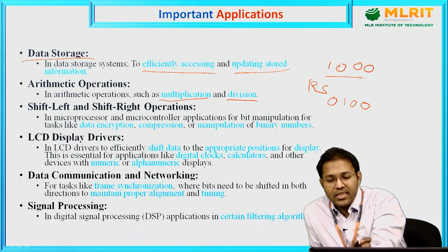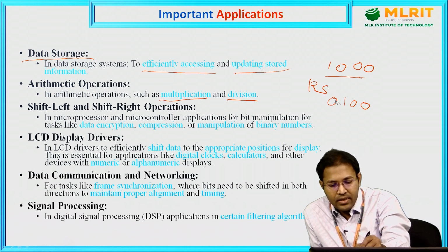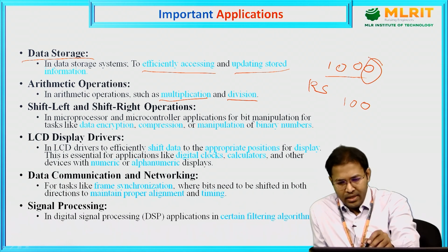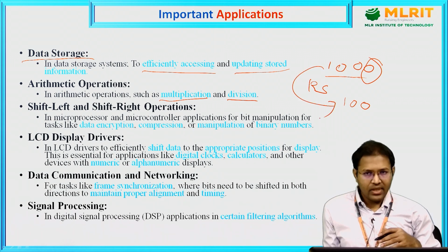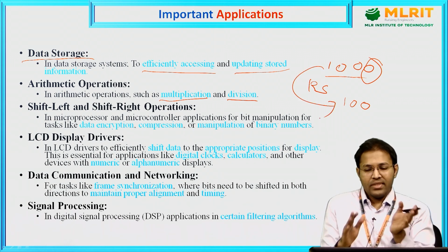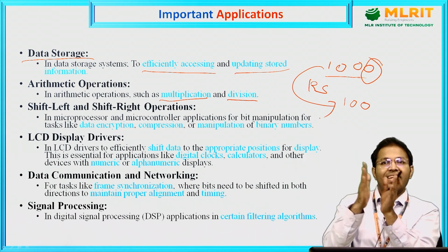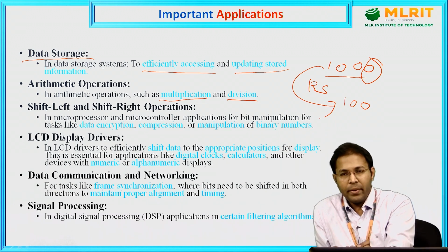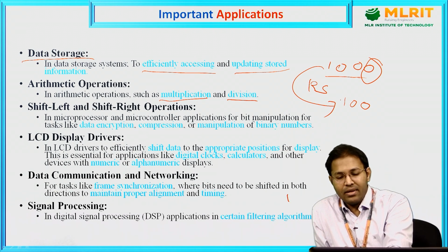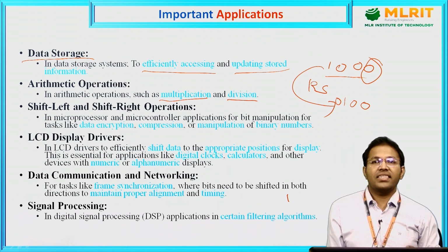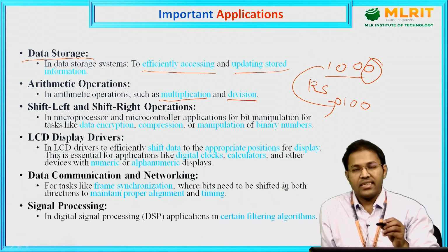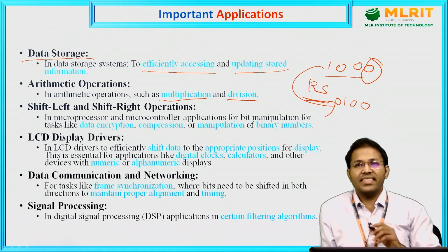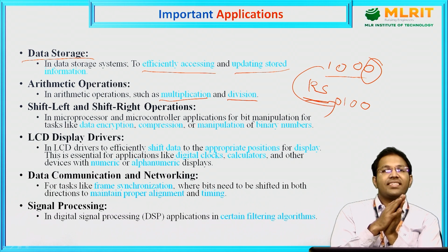So actually we are supposed to get this. The last bit goes out of the sequence because we are shifting towards right. So one value is leaving the flip-flops. But in such a case, we take an extra 0 at the left. And that is the reason right shift gives us this sequence: 1 0 0 0, right shift gives us 0 1